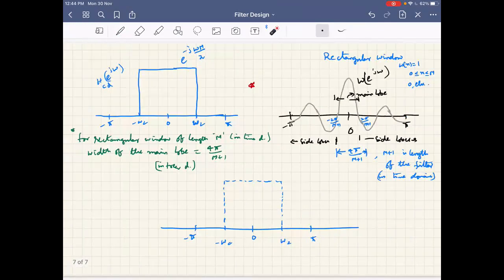Okay, fine. So now what will happen once this main lobe starts touching this filter where it is non-zero, the desired frequency response, the value of the convolution starts increasing. And when this completely comes and sits here and starts sliding, assume that when the zero is exactly here, it means that half of the main lobe is this side. At that point, if you slide further, the attenuations or side lobes start coming in, and hence the frequency response keeps oscillating. And then when the main lobe starts coming out, the frequency response falls down.